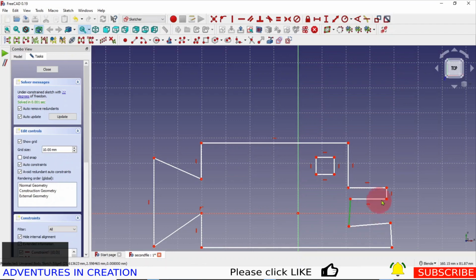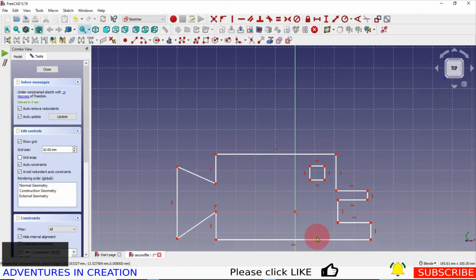So this one should have a vertical constraint. And this one should have a horizontal constraint. And you see it automatically forces them to be horizontal or vertical, depending on what we pick. So those are all the simple ones. And I can see from my sketch that this should be up here somewhere. So it doesn't really matter where it is right now.